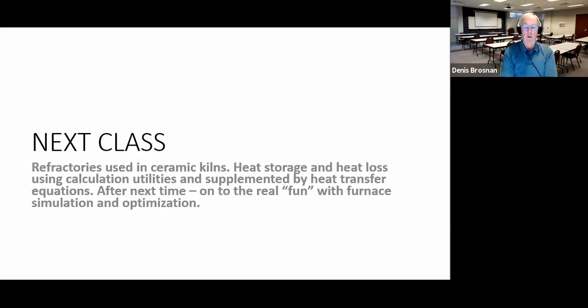Okay, well, we've talked about getting the heat to the kiln. We've talked about containing the heat in burners. We've talked about injecting the fuel into the burners and controlling that combustion. It's a little different with solid fuels and liquid and gaseous fuels, in that with solid fuels, we had to depend on the air in the kiln itself to cause the burning of the fuel, the oxidation of the fuel, whereas in liquid and gas fuels, we injected air into the burner system.